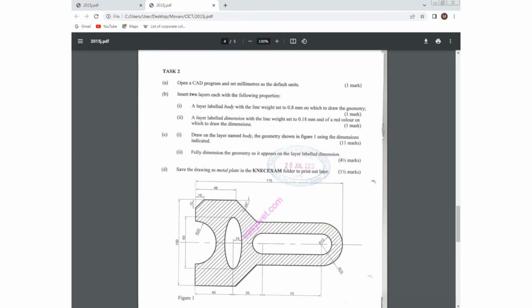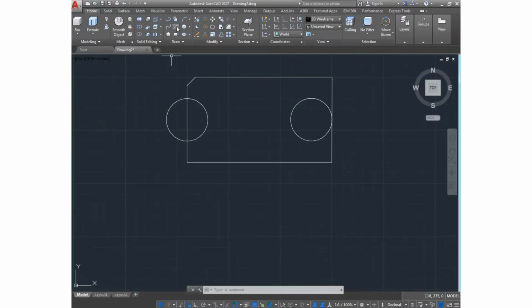So I will return to the AutoCAD program, select the line, put it on that corner, go sideways a distance of 45, then click enter, then go just any distance. This line is for knowing where the circle is supposed to start, so click there and then enter. I hope my line is straight.